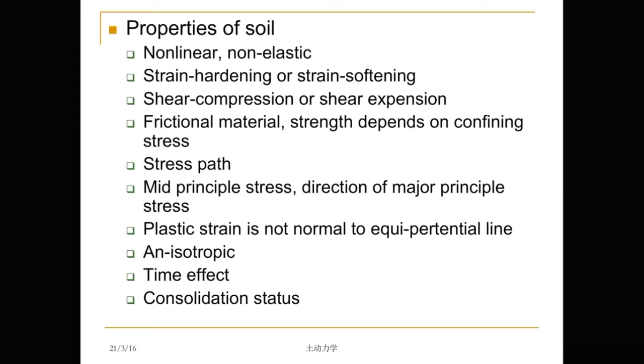And this shear strength, like a frictional material, if the normal stress is higher, then the shear strength also increases. That means the shear resistance depends on the normal force. And the normal force just depends on the confining stress.